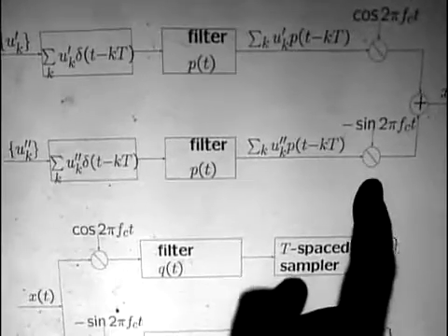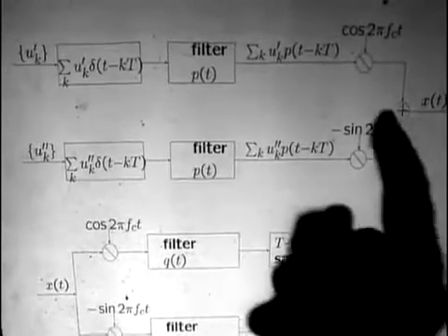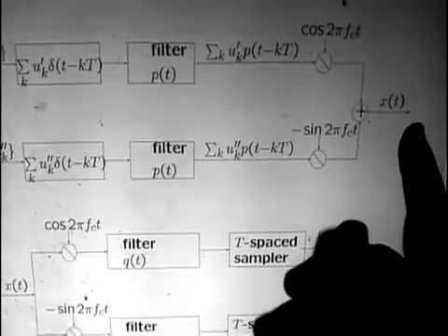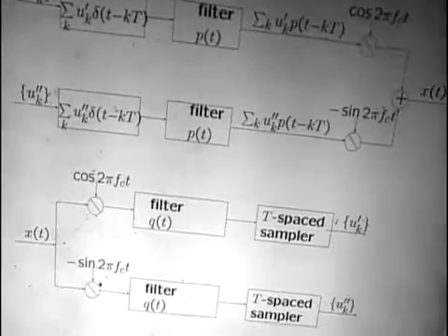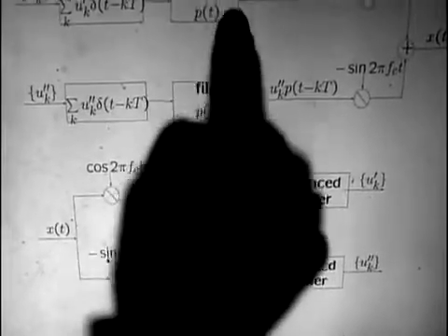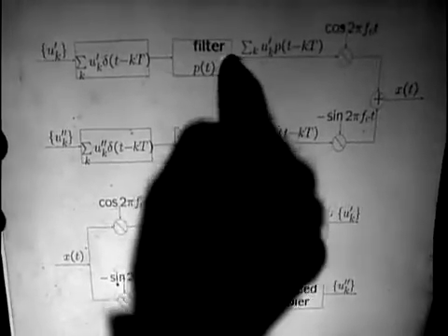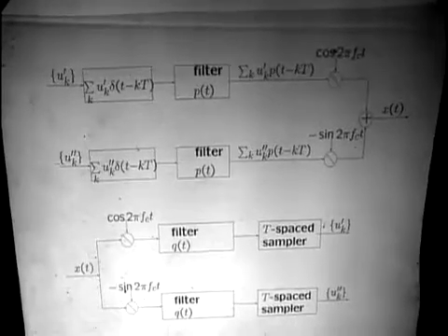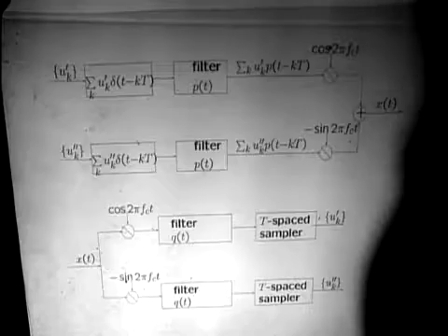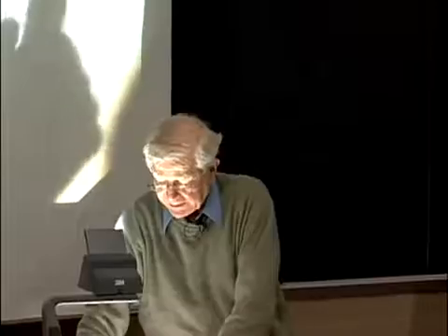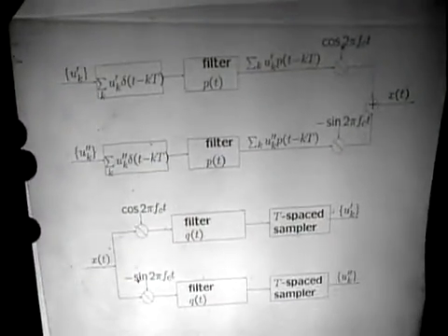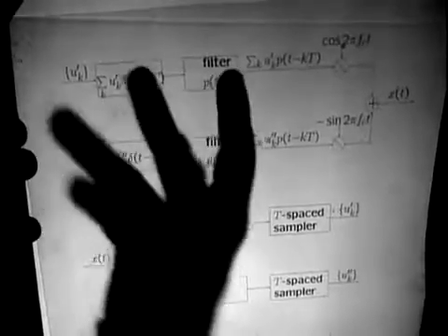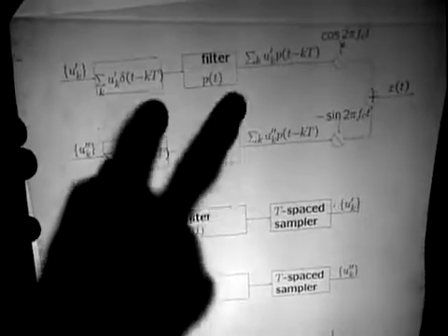We multiply this by a sine wave, and what we get then is some output x of t, which is in the frequency band that, if you take the low-pass frequency here, which goes from 0 up to some W, up at passband, we go from fc minus W to fc plus W. Same thing here. So we have this function, which is passband constrained to twice the frequency, which we have here.